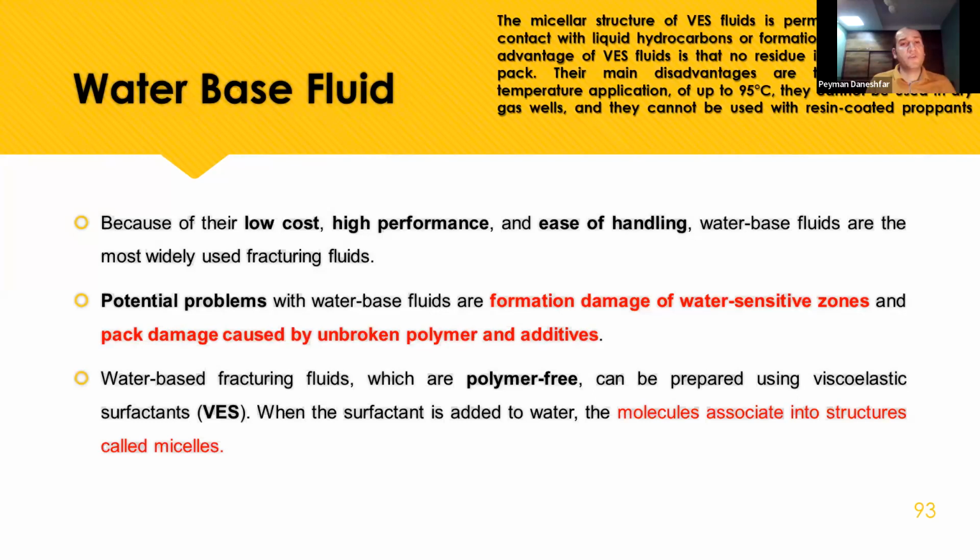Water-based fracturing fluids which are polymer-free can be prepared using viscoelastic surfactant. Viscoelastic surfactant is used in acidizing, but when we want to break the viscoelastic surfactant, we can add some mutual solvent to break it. And when the surfactant is added to water, the molecules associate into a structure called micelles.